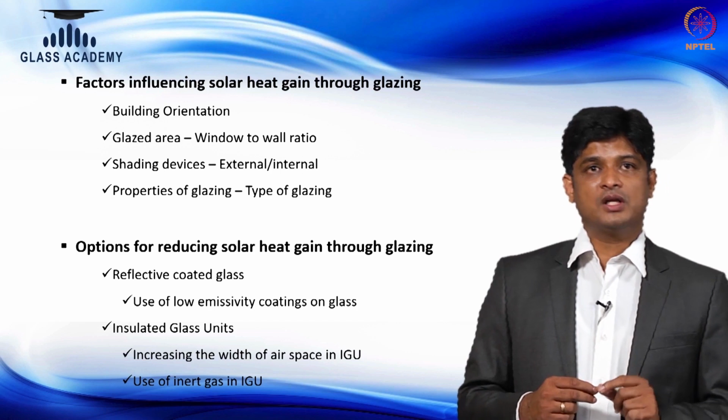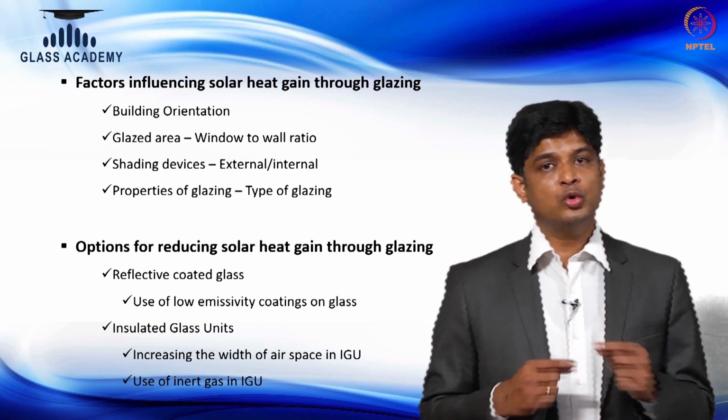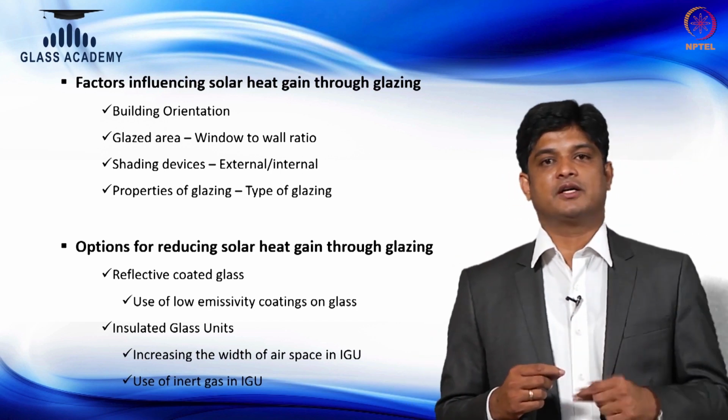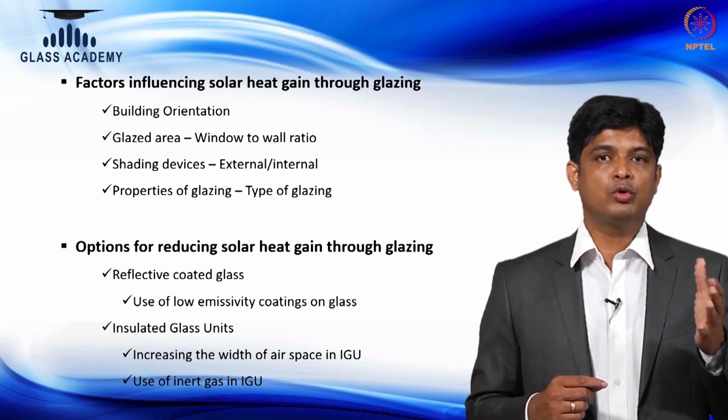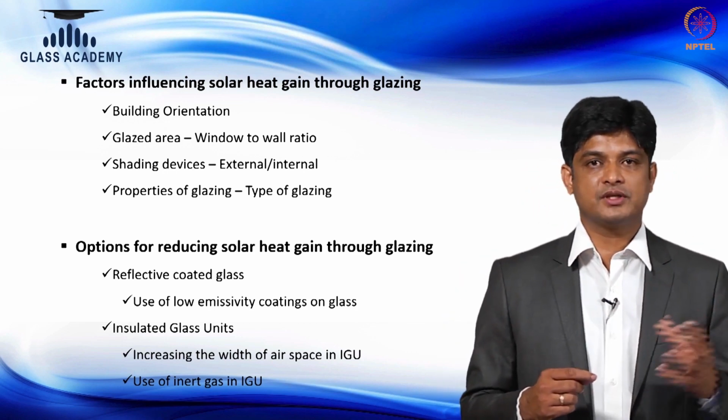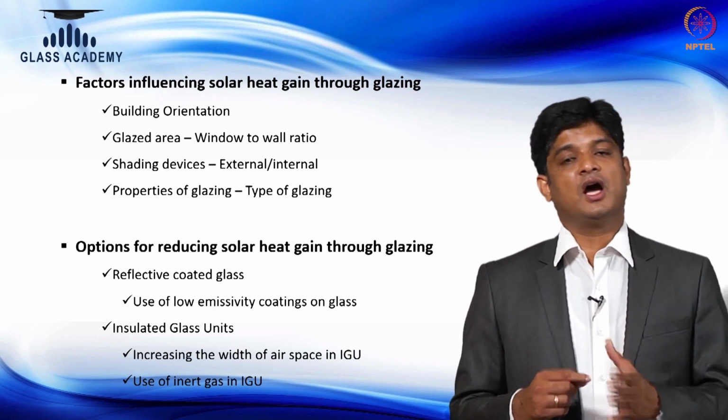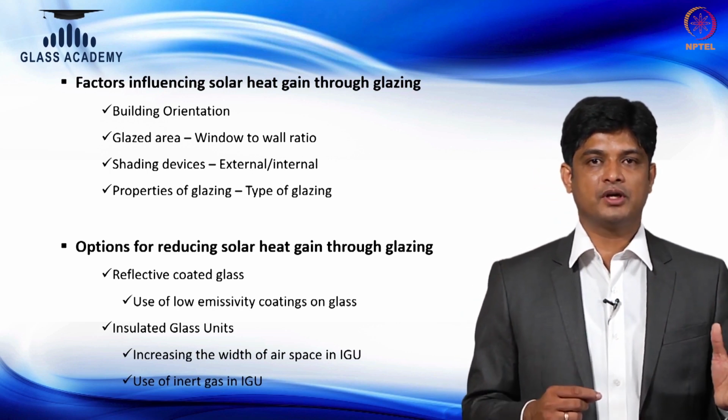Second one is, what are the other options that we can do to reduce the solar factor? One is, I can play with how to reduce the heat coming in. There are some provisions available. Okay, I have a restricted orientation, or I need a particular window wall ratio.